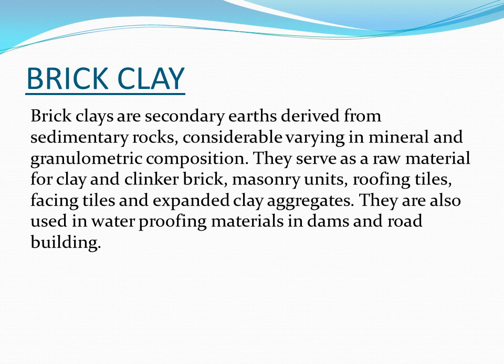Next is brick clay. Brick clay is a secondary earth derived from sedimentary rocks. Potter's clay was redeposited material and this is derived from sedimentary rocks. Considerably varying in mineral and granulometric composition, they serve as raw material for clay and clinker brick, masonry units, roof tiling, facing tiles, and expanded clay aggregates. They are also used as a waterproofing material in dams and road building.